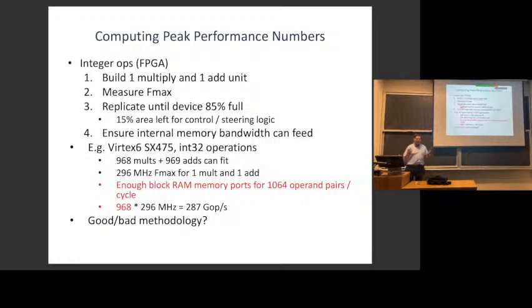And it's basically based on their experience. It's going to vary a lot from application to application. So clearly there's a pretty big margin of error on that. And then you also pointed out something important, that as you fill an FPGA up, the clock frequency does tend to drop for two reasons. You can get routing congestion. So there's just some problem getting the exact wiring you want.